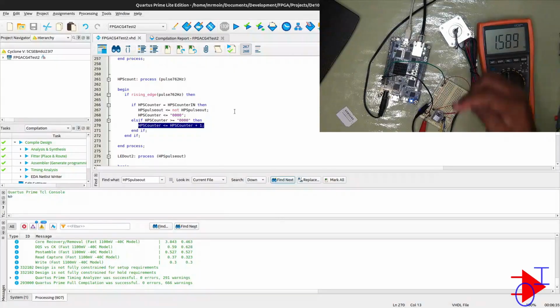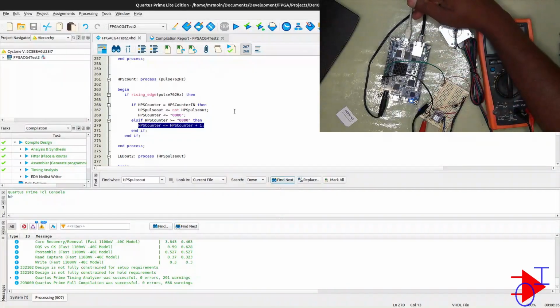Essentially what I'll do is use this UART connection and write up a program in C++ in the HPS to read the UART, and the UART will define the exact speed through commands, a set of commands which will be exactly the same as the Arduino commands.